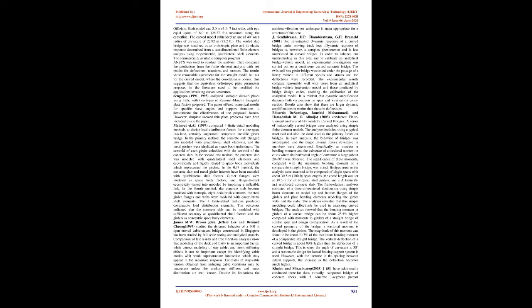structures. Sengupta, 1991, 1995, analyzed isotropic skewed plates using FEA, with 2 types of Reissner-Mindlin triangular plate elements proposed. The paper offered numerical results for specific skew angles and support situations to demonstrate the effectiveness of the proposed elements. However, only the simplest skewed thin plate problems have been included in the paper. Mabsout et al.